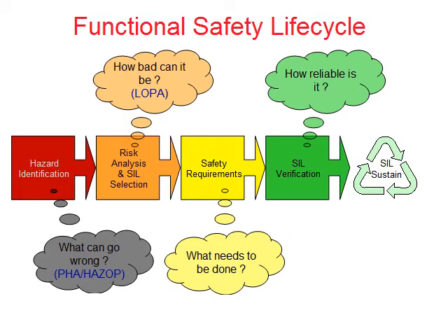So there would be the reliability, the safety reliability of the gas sensor, of the logic solver, of the valving or fanning or alarm system or personnel response. But there also has to be considered is how likely is it that that sensor or array of sensors is going to be able to pick up the gas that's the hazard we're looking for.